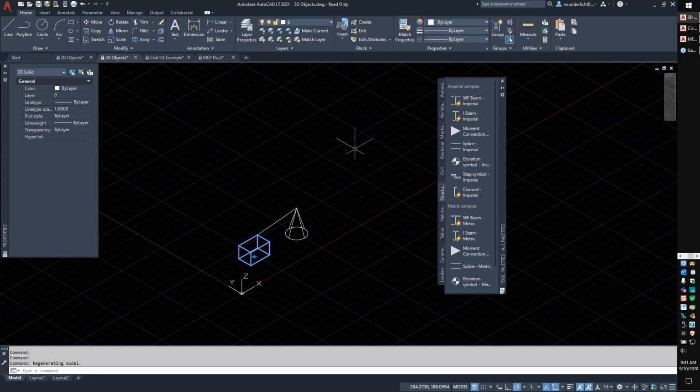Basically, what I talk to people about as a former CAD manager is, if you're going to enforce standards, the first thing you need to do is know what it is you want to accomplish. Anytime I've come into a job as a CAD manager, I like to set up a block library, make sure that all the blocks in that library are the ones we normally use. Once I've done that, then we talk about layers and things like that. But yes, as long as you have that block library, you can put those landscape features and symbols in. You've just got to draw them the first time manually, save it as a block, and then you can use it in the future all you want.